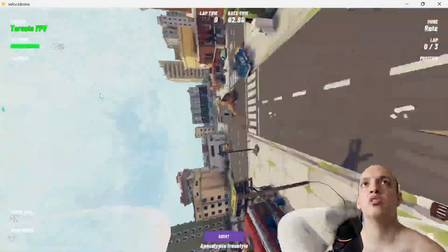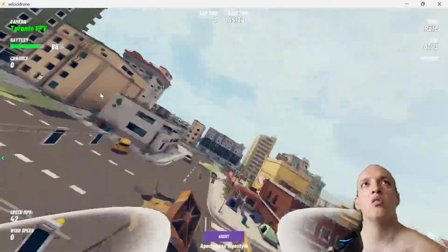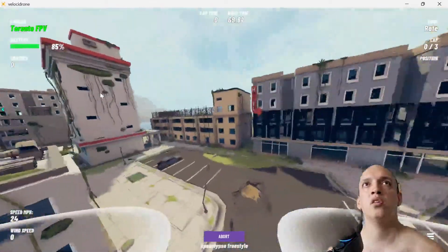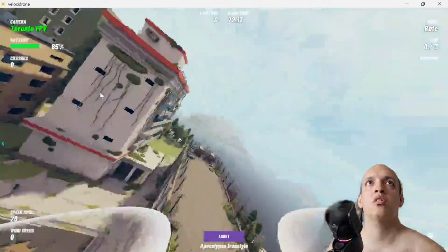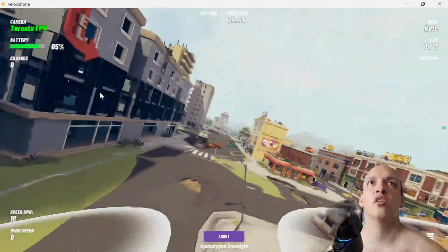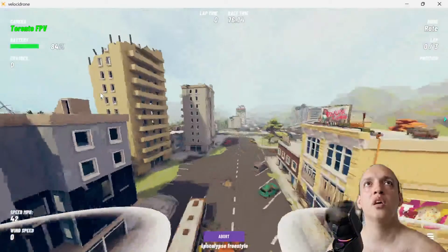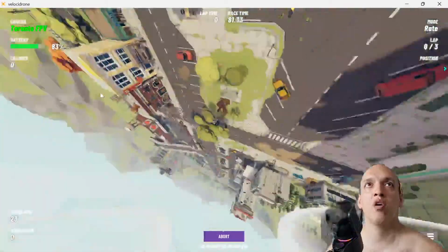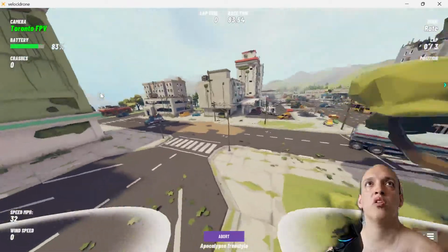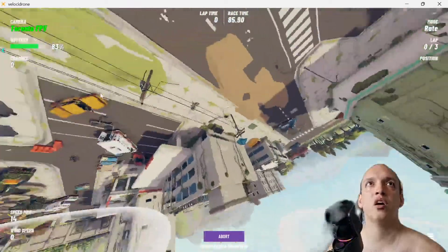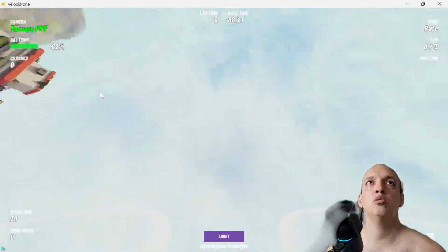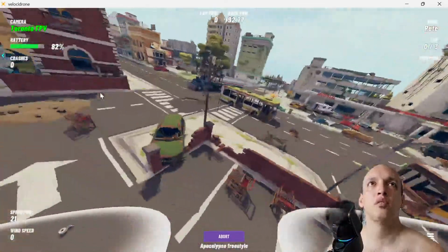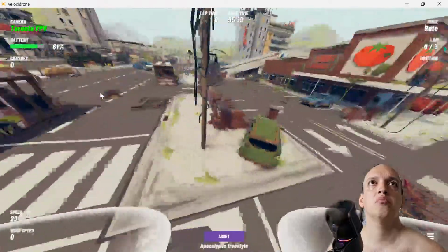And just that bounce. Throttle up, cut the throttle, turn. Throttle up, cut the throttle, turn. Catch yourself. The throttle is going to keep you up. And then you want to be able to fly around and turn, you cut that throttle every time you do those movements. And then when you come out of them, throttle back, catch yourself, bounce a bit. Woo, right? And then when you're lower, then you can start doing stuff.